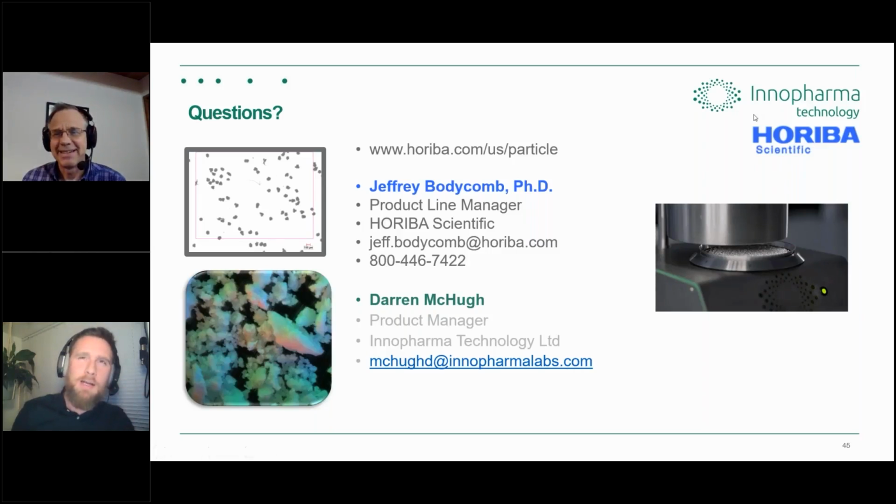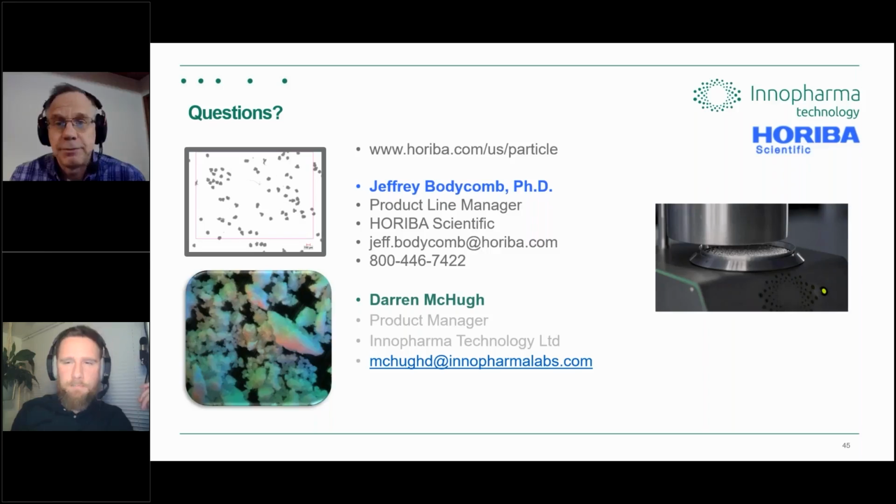Yeah, I don't remember the icon's numbers offhand, but it's a little larger. So our pixel size is 5.5 microns, so our resolution is like 11 microns. But it's the same thing. If you put an 11 micron particle in front of it in perfect conditions, you'll measure it. But the repeatability of that is very hard, hence we say the lower limit is 50.